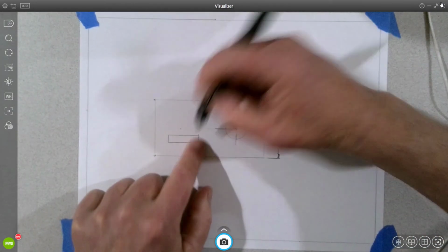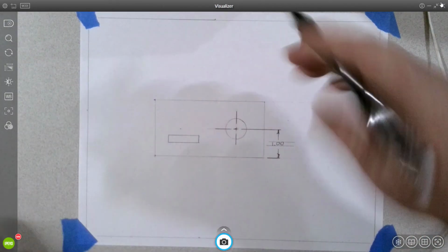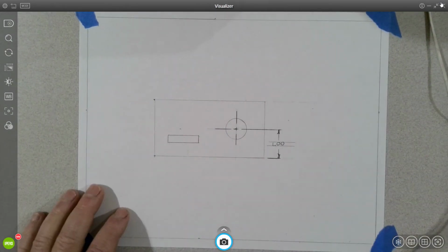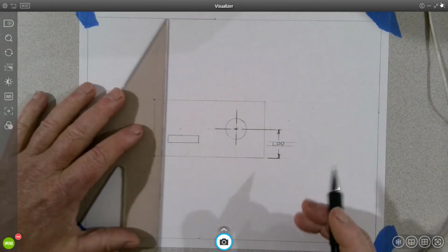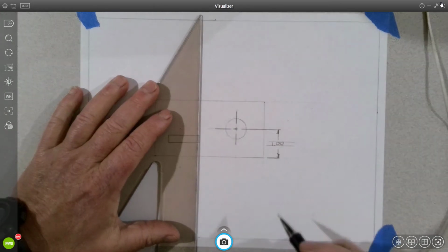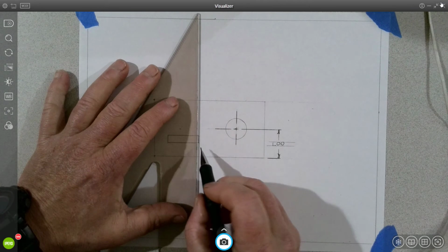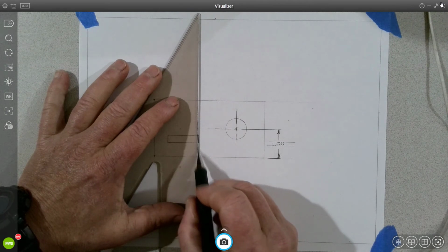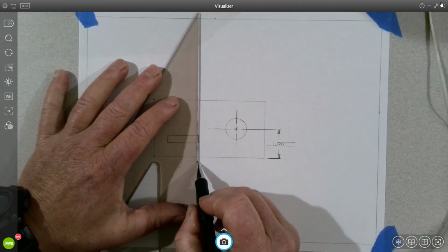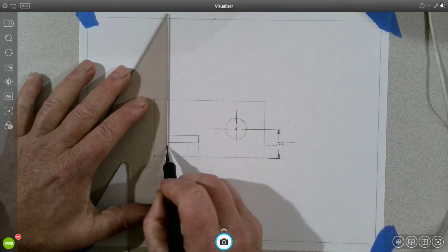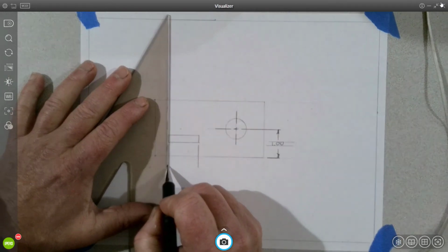That's called an overrun, and we don't want them. Nothing is darkened yet. Nothing is darkened yet. But the dimension line, right, to locate this or to dimension it, I'll just size it right now. Again, I'm just trying to find vertical here by eye, which is never great. But the extension line goes all the way to it with a gap. Extension line all the way to it with a gap.